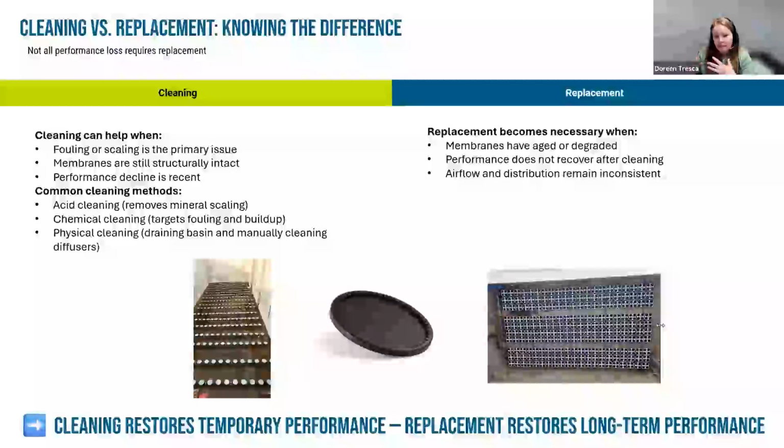So the key distinction to know whether I should clean them or replace them is: cleaning can restore the performance. Replacement restores long-term system performance and stability, and replacement is something that we would recommend when the actual membrane is damaged beyond the point of cleaning. So when it's stretched out, if the slits are stretched out, that's when you should really start looking at replacing the diffusers versus just doing scheduled maintenance.